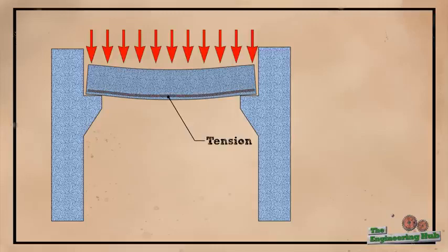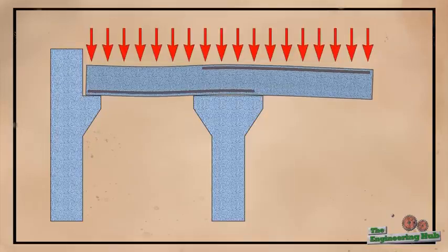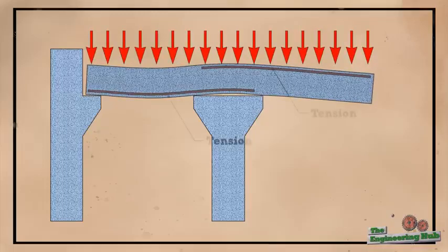But for some more complex arrangements, steel reinforcement could be required on both sides of the beam, if tension forces are to be expected. One such example is a cantilever beam that has the top material in tension or stretching and therefore has the top part of the beam reinforced.